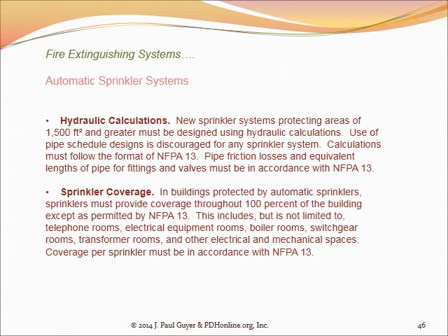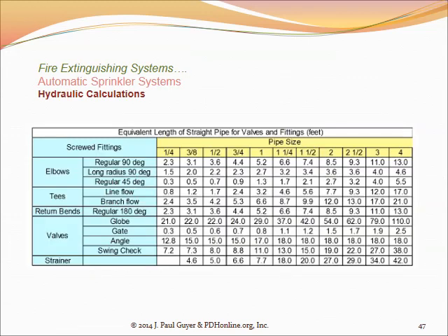And so we're all familiar with fire sprinkler systems in buildings and the piping that's running around. And one of the challenges, and this is about the only place that any theory comes in at all in fire protection engineering, is how do you size the pipes that are carrying the water running around in the building. And the situation you've got is you've got the water that's being supplied by the local water utility right at the exterior wall of the building, and that water is being supplied at, say, 50 psi. Well, and then we just looked at the design densities that were required, how many GPM per square foot of water were needed to be put on the fire.